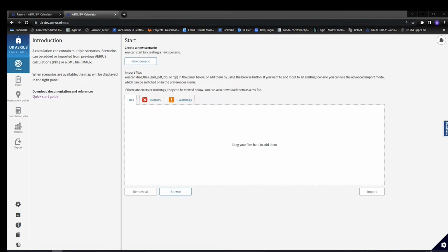It does include a lot more than just acting as a front end to ADMS. It pulls in all of the habitats information that you normally have to go to APIS to get. It has that mapped out. The results are plotted in terms of impacts on CL, both as a process contribution, a scenario contribution, and in combination process contribution. That would all have to be done through some sort of post-processing step. So that offers a lot of functionality that doesn't exist for most users outside of a system like this, although I recognize some places may have their own post-processing tools for that.